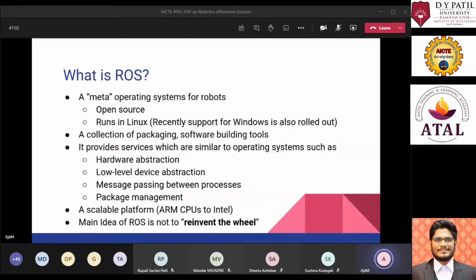Over here on the topic, you can see this message. This message has a number, which is an integer, a width which is a double, and a description about that message which is a string. One of the examples of a ROS message is the pose example. Let's say you have a robot in a 3D world. That robot will have a point in free space, or a pose in the 3D world. That could be X, Y, and Z in the 3D world. And this X, Y, Z are all float64 data types.